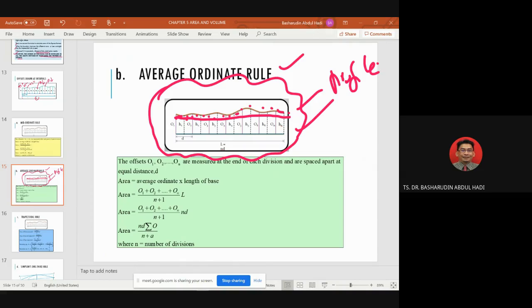That's why when you design the cut and fill line, something you want to put like an embankment, you must discuss with your clients how much they want to spend on the landscape works, or earthwork, based on average ordinate rules. Okay, the offsets O1, O2, ON are measured at the end of each division and are spaced apart at an equal distance D. This one is D, the same. This one you count 1, 2, 3, 4, 5, 6. So they should have 6, from O1 until HN.